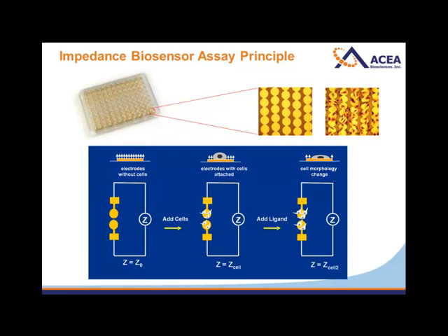Every 4 wells is shared by a common ground. And so to connect the electrode array in the wells to the instrument, we've got contact pads here. And the instrument has a very simple spring-loaded pogo pin. And so that's how we form the electrical contact. So I'll pass those around. You guys can take a look at them if you want.